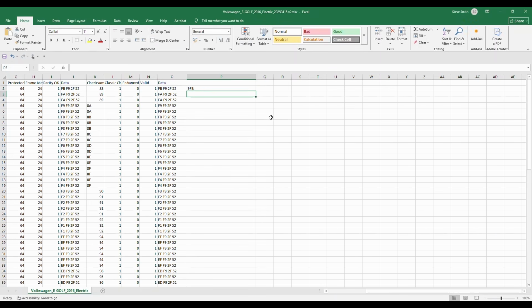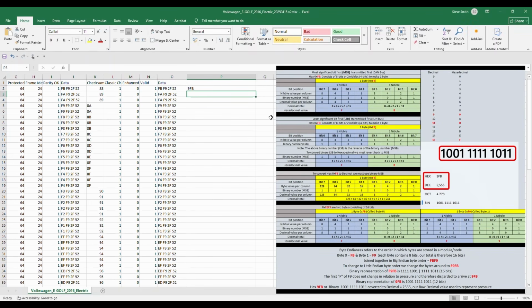So you'll see in a second that what we're doing there is swapping hex values around. Why is that? Well, Pico has displayed the hex bytes as most significant byte first, which is typically how you do conversions when you go from binary to hexadecimal. However, the LIN protocol works with little endianness, so least significant byte first. So really, what should have happened there is FBF9 became F9FB.